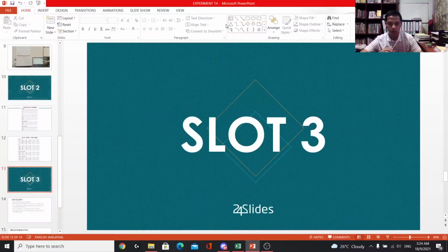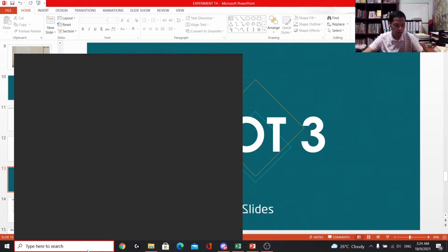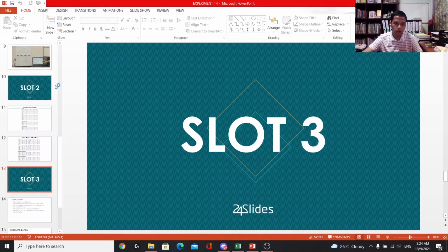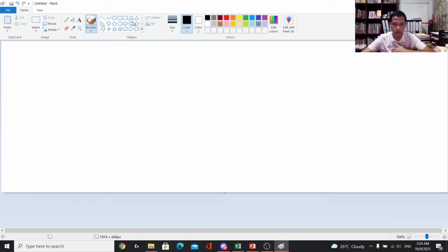Here we go to the calculation. As you can see, the formula is η equal to 1 minus 1 over rp to the power of (k minus 1) over k. For number 1, rp is 4.